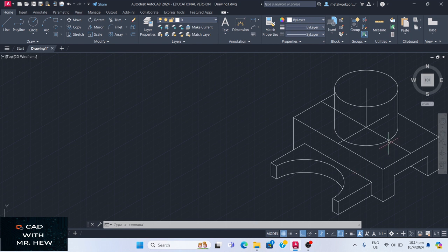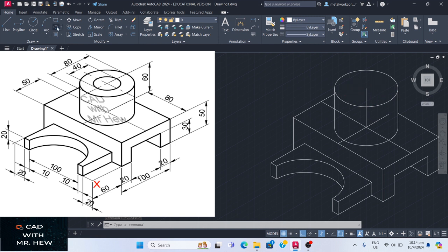All right, so what I'm gonna do, I'm gonna put these lines on the center line, right? And in a little while you'll see the reason why I did that. All right, next thing I'm gonna do, I'm gonna draw the circle at the top, right? So we click this, click ISO circle, specify the center, good. Then the diameter, that is what it is asking for. So these in the square bracket, it's asking for that.